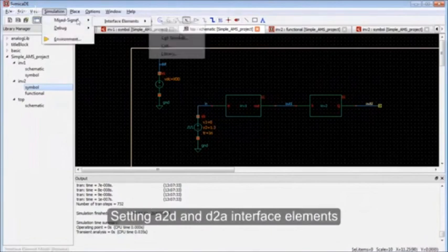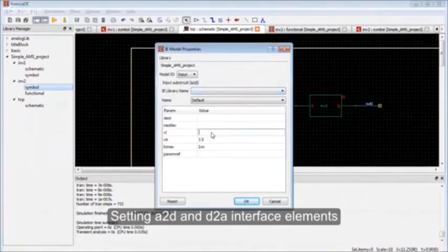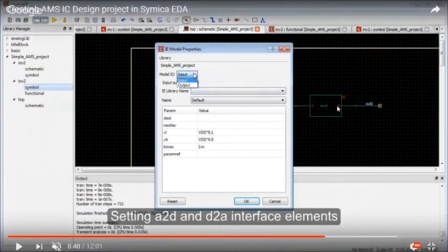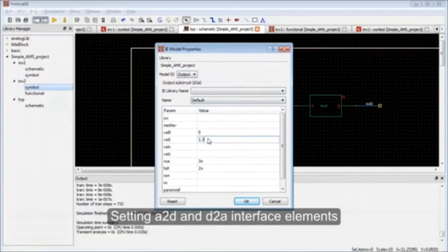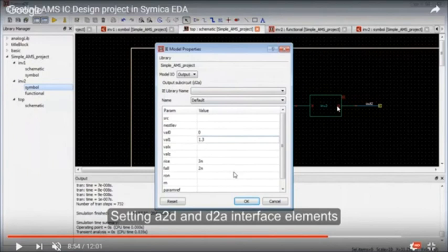The interface is there. Here we have defined the lower level as 10% of the VDD, and the higher level as 90% of the VDD. Okay, so like this we are giving it, and it will understand where it will find a low signal or a high signal. Similarly for the output, we want analog again. So we directly define the voltage range, 1.3 volt.